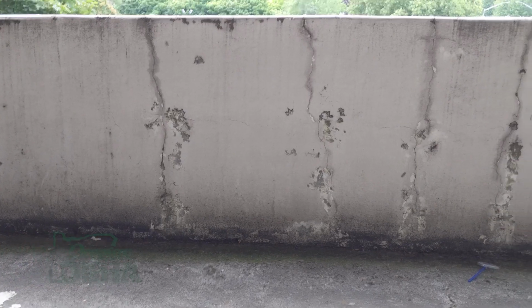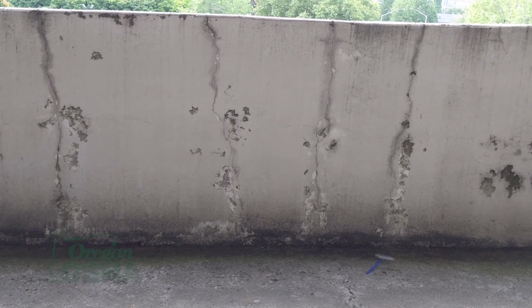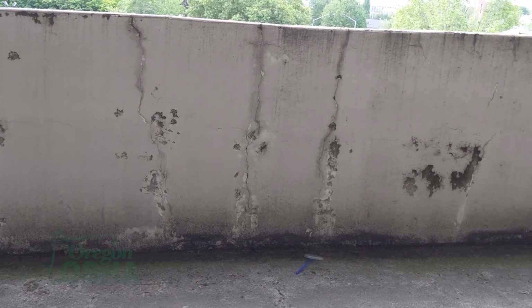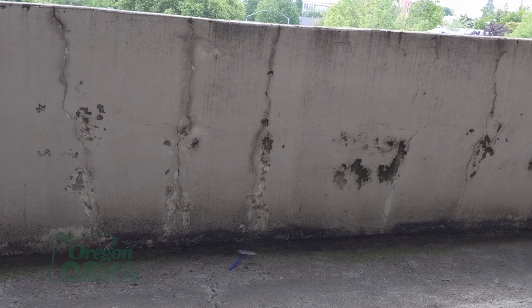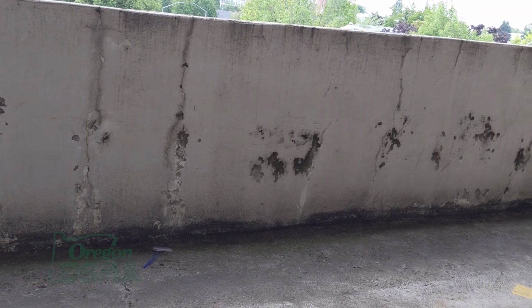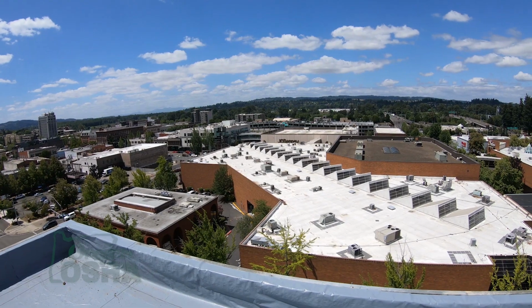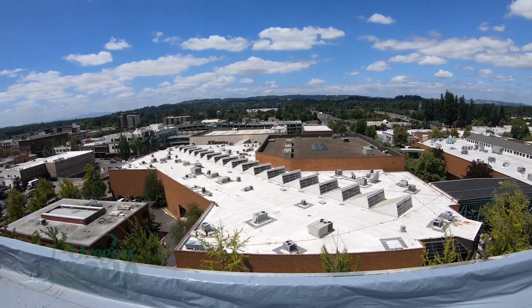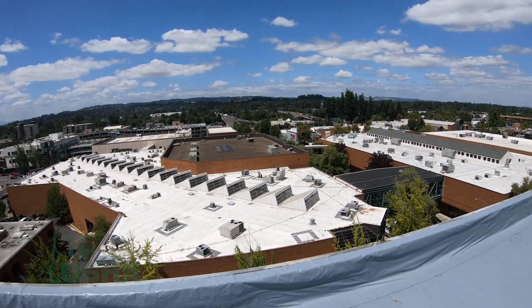You cannot count the width of the wall anymore in your measurement for your parapet wall for safety. As long as that parapet wall reaches a nominal height of 42 inches, then that will count as your fall protection, and you don't have to wear the harness, or you don't have to have a tie-off anchor, and you don't have to have a warning line if your parapet wall reaches that nominal height of 42 inches. So if you have a parapet wall and the height is only 30 inches, you're not tall enough to meet that nominal of 42, then you have a few different options.